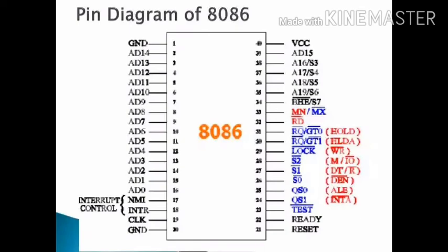It means the next byte of opcode would be taken from the queue. So these signals will indicate the local bus cycle status. Whenever the 8086 is controlling the local bus, the 8288 bus controller will generate bus control signals using these signals sent out by the 8086.